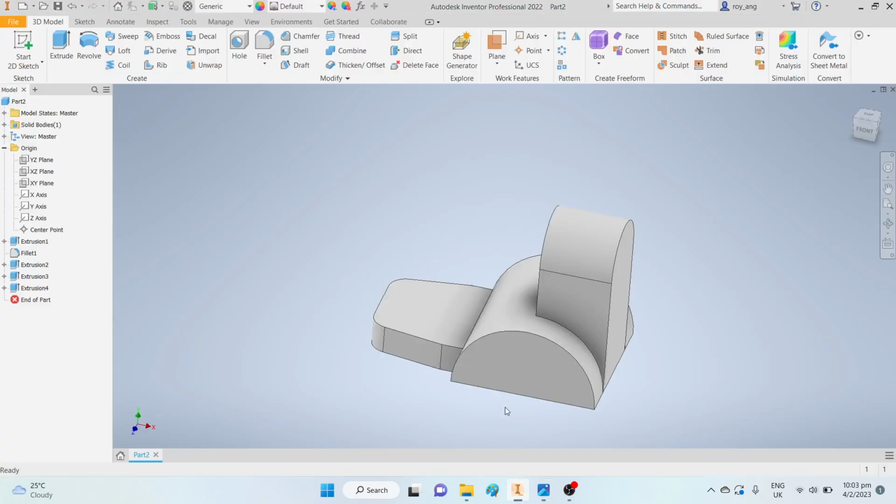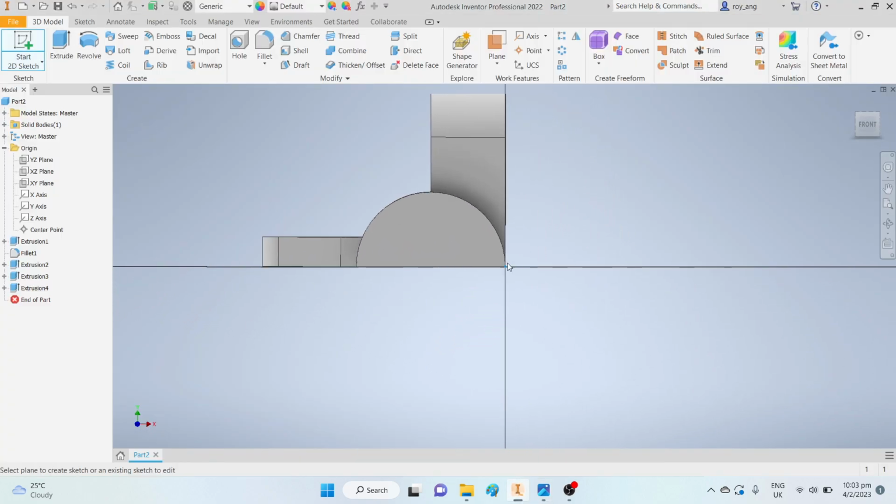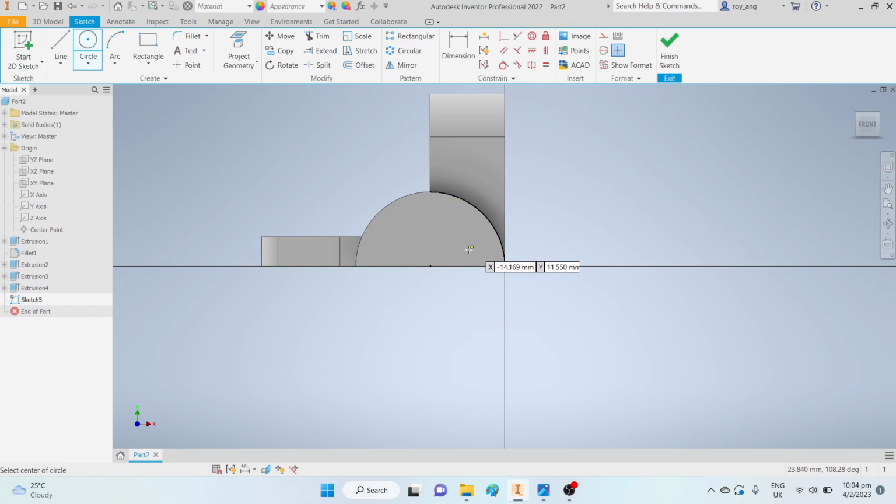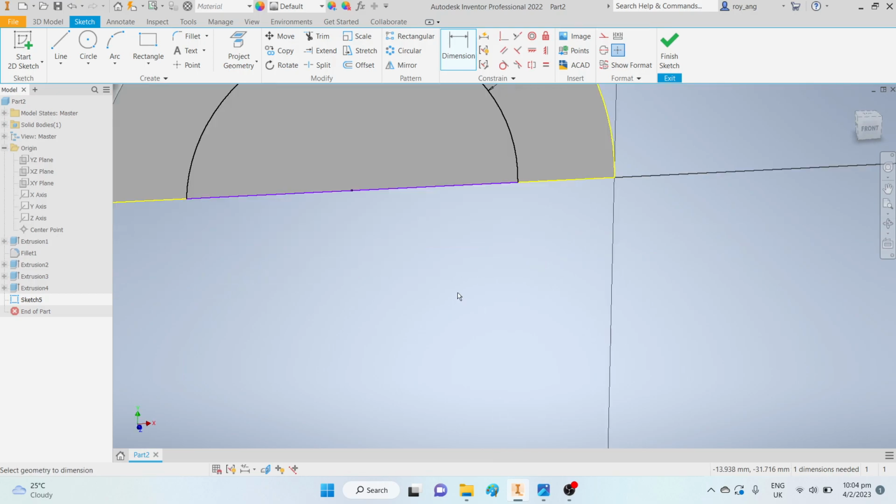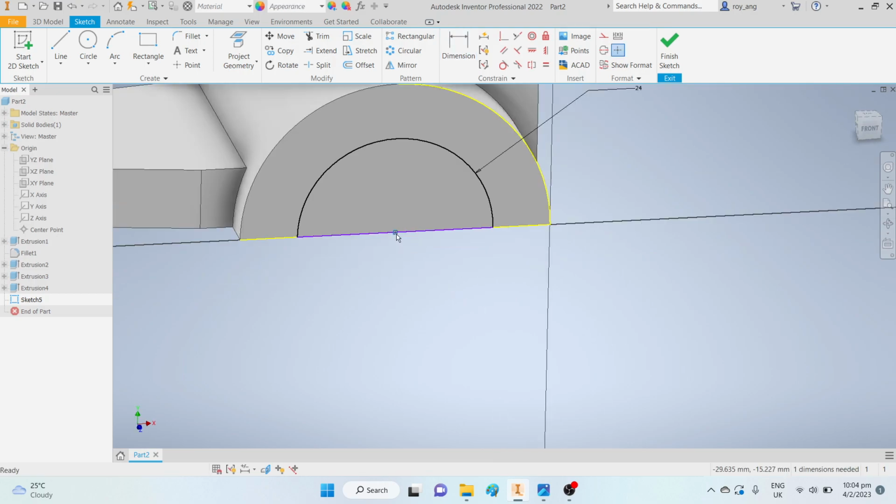So what I can do is I can put this sketch here, draw a circle, and draw a line that bisects the circle into half, and then I trim it. And after I trim it, when I add my dimension, it will be in radius, and I'll put radius 24. Okay, right? Now the line here is not blue, and that's because I may be able to move it, or there is actually a projected line here, and I'm going to connect it again.